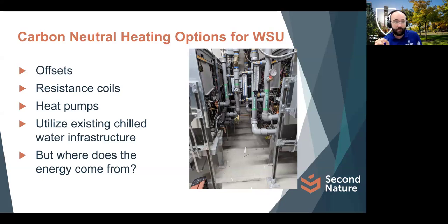The nice thing about heat pumps is their tolerance for the temperature of water they need is really broad. These particular heat pumps are good until about 47 degrees Fahrenheit, and we try to keep the loop at 50. But they can operate quite well with warmer water. If my loop is 70, 80, 90 degrees, I don't care much. But if I'm heating in the winter, I'm cooling that loop down, and eventually it gets so cold the heat pumps can't work. That's where this idea of ground source comes in. Let's go to the next slide.